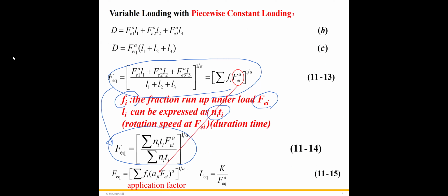Okay, so here we need to apply the safety factor. This is the FEQ, the equivalent load, and we need to apply the application factor, or we say the safety factor. So this force FEi has to be replaced with the safety factor times FEi.